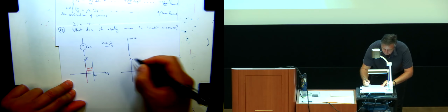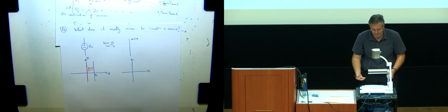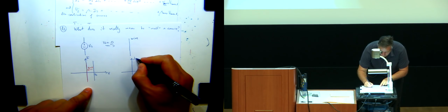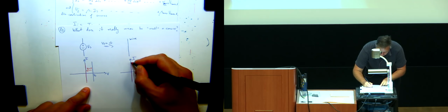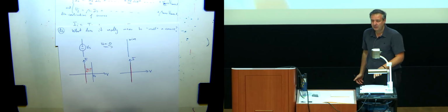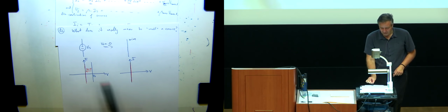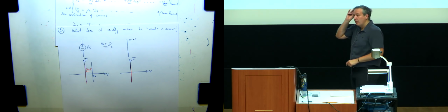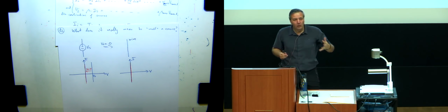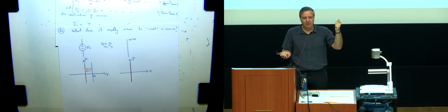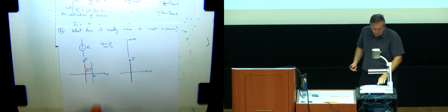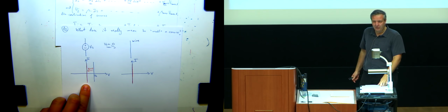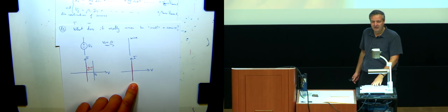This is just, we're recalling a definition of a wire, right? In its IV, a wire has voltage of 0 across it and can pass any current, right? So these two are identical. And remember, any element is only defined by its IV function, right? That's the only definition of the element. So I'm not really cheating you when I say that voltage source of value 0 is exactly the same as a wire, right?